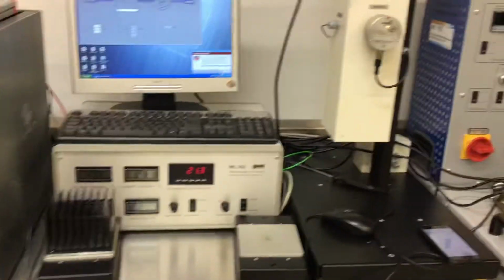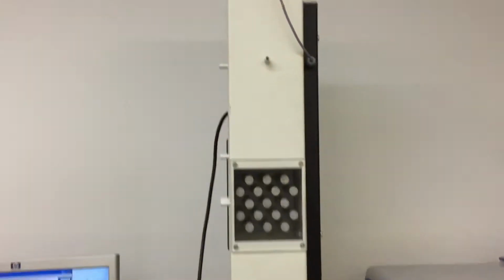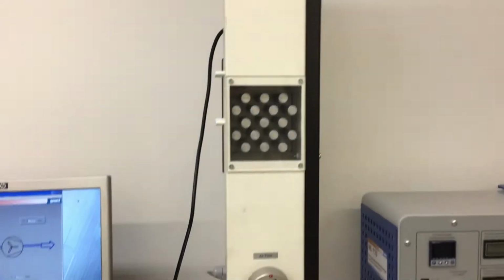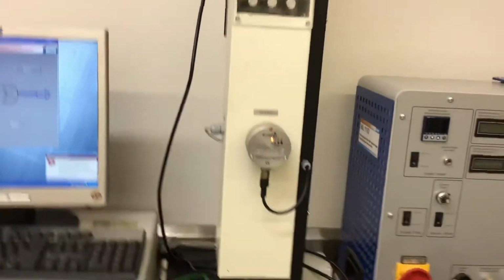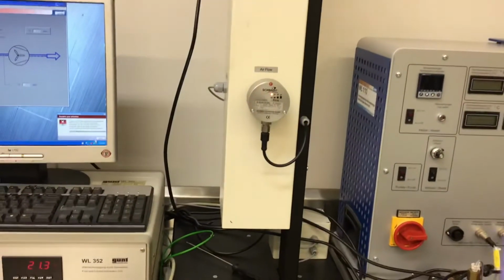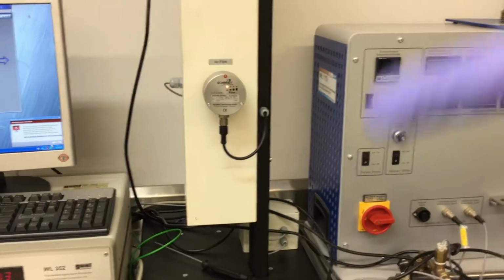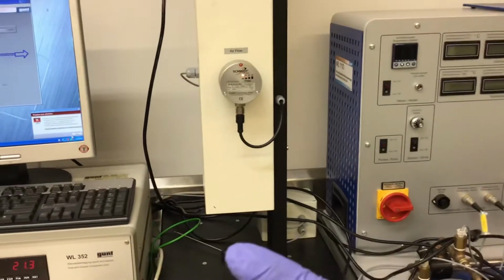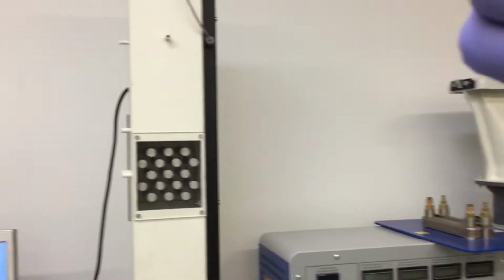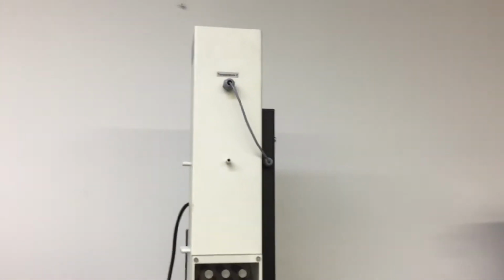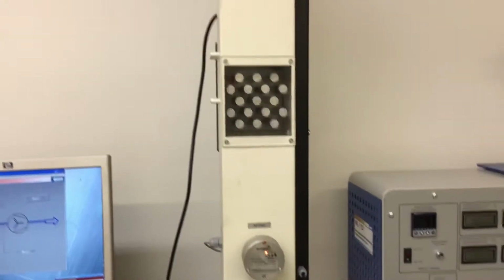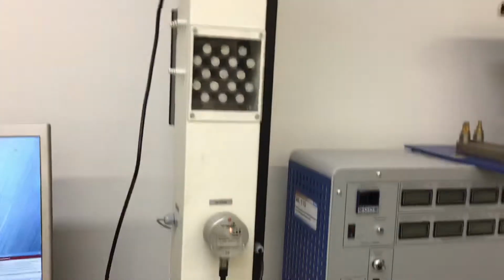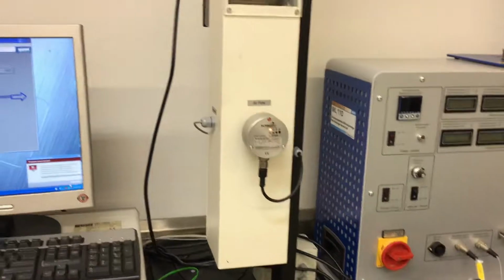The setup, you can see it's right here on the right-hand side. This is a duct that is meant to have a controlled environment where the flow of the air goes from the bottom and all the way up in that direction. So it goes from the bottom here and up through the heat exchanger that is embedded in the system, or kind of installed in the back of the system. There is a fan inside, actually located on the top of the duct, to create a kind of laminar flow. You also have a honeycomb structure at the bottom, very similar to a wind tunnel configuration.